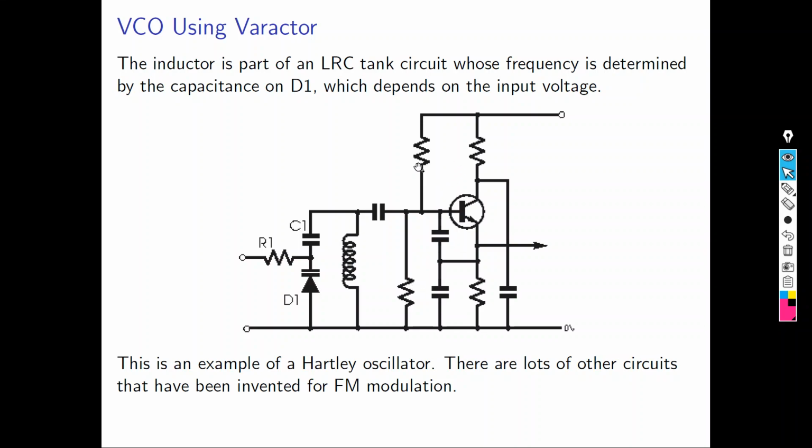This is the electronic circuit that you can design and fabricate. You can buy these resistors, this transistor, this capacitor, and solder them together. You can connect them with each other on a breadboard or PCB, connect them with an antenna, and you will have an FM transmitter. So now you can go home if you want and build an FM transmitter.